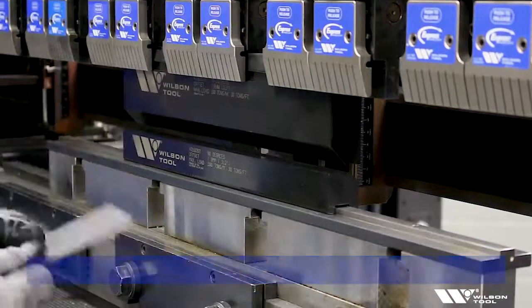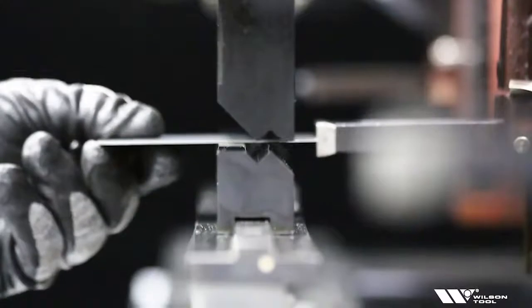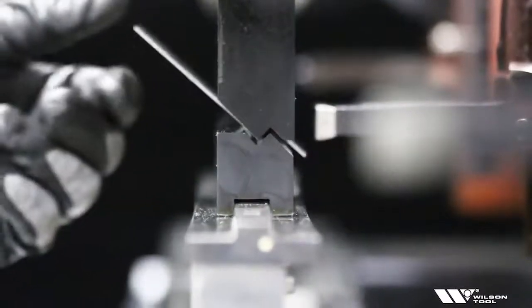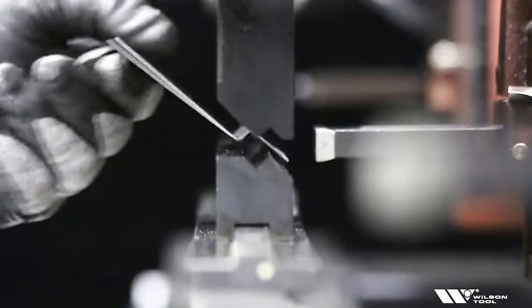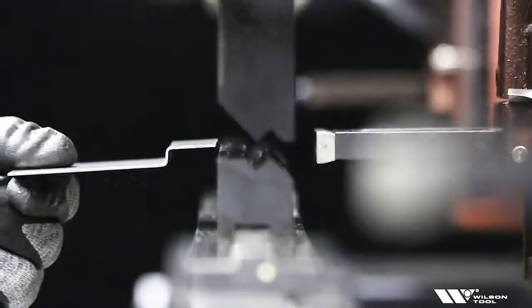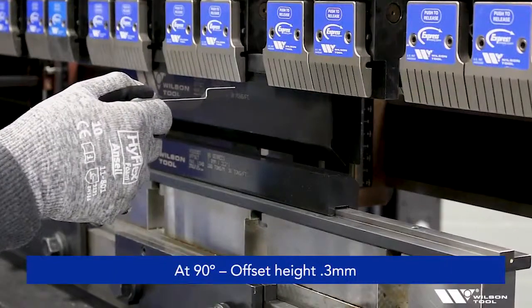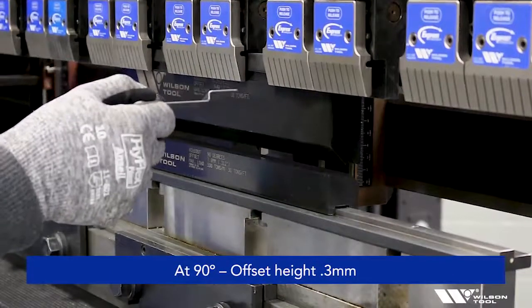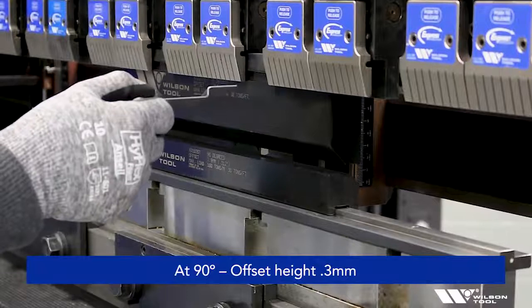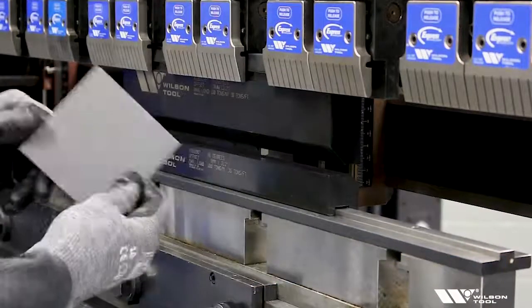We're going to take a little bit off of that stroke now. Let's make it a little bit closer to the 313 offset that we know that we can generate with this tool. And now you can see that's pretty close to 90. So we've just controlled the stroke, basically the tonnage in this case, because we created a little bit on the last one, not so much on this. Let's back it off another little bit.